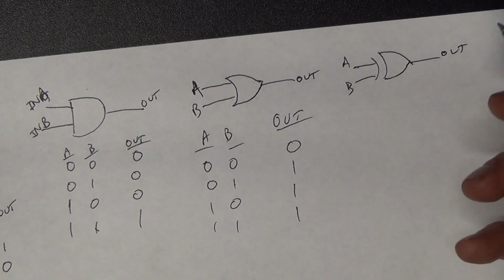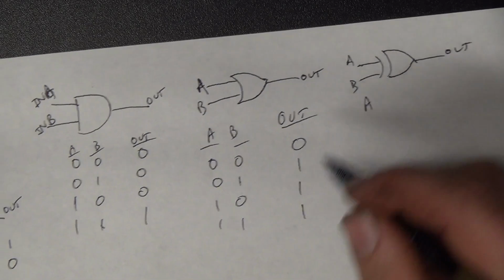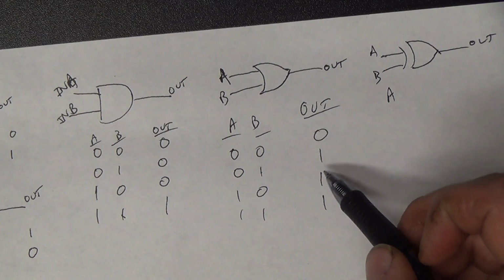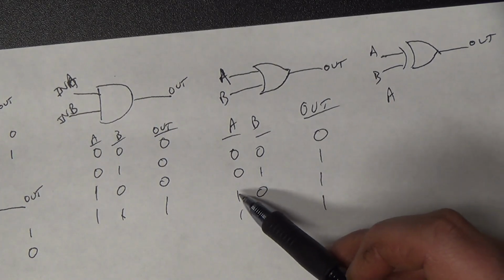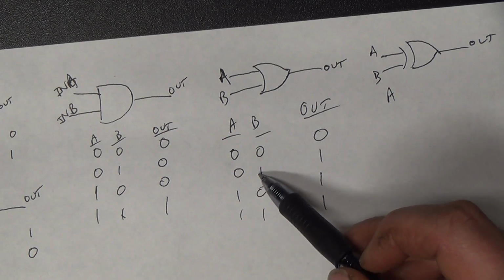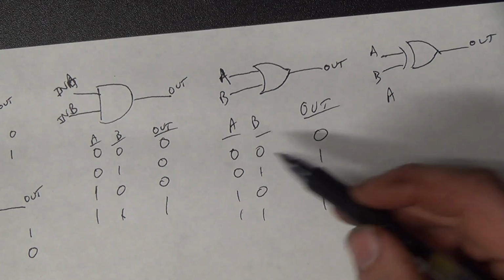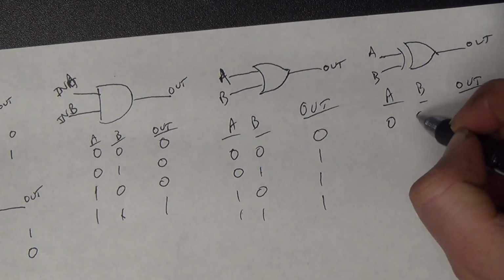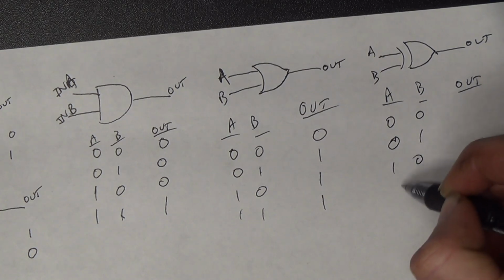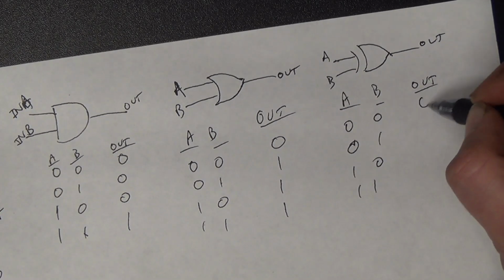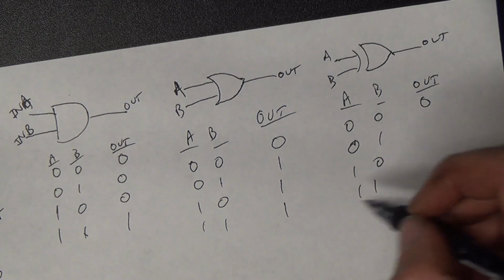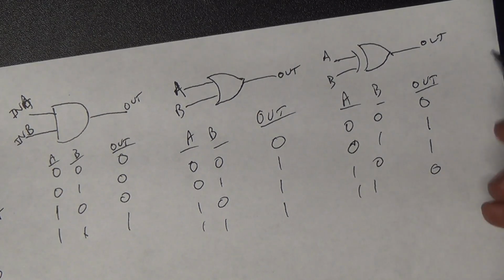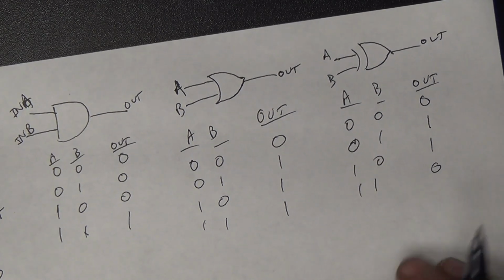The exclusive OR gate is like an OR gate, except it only outputs true, that is, pressurized magic smoke, if A or B, but not both, of the inputs are pressurized. So the truth table for it would look something like this. This would be a 0, neither are pressurized. With both pressurized, we only want one or the other, so that's going to be a 0. But when one or the other is pressurized, the magic smoke comes out pressurized, like so.